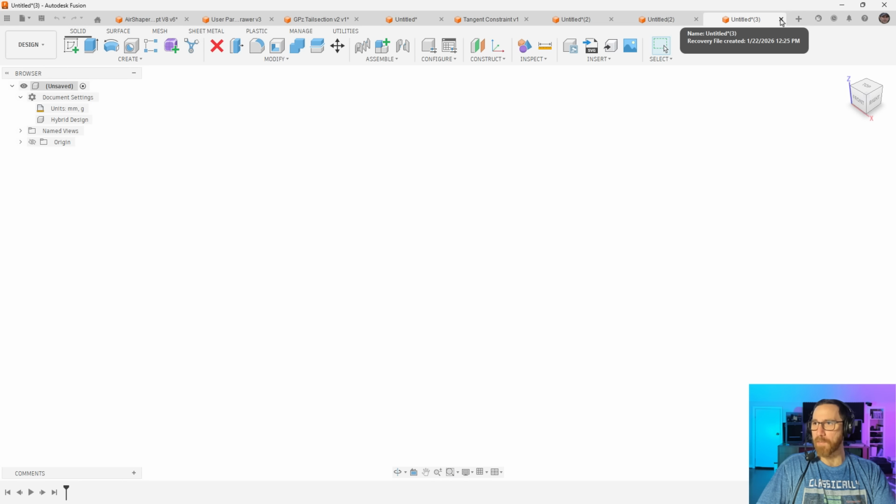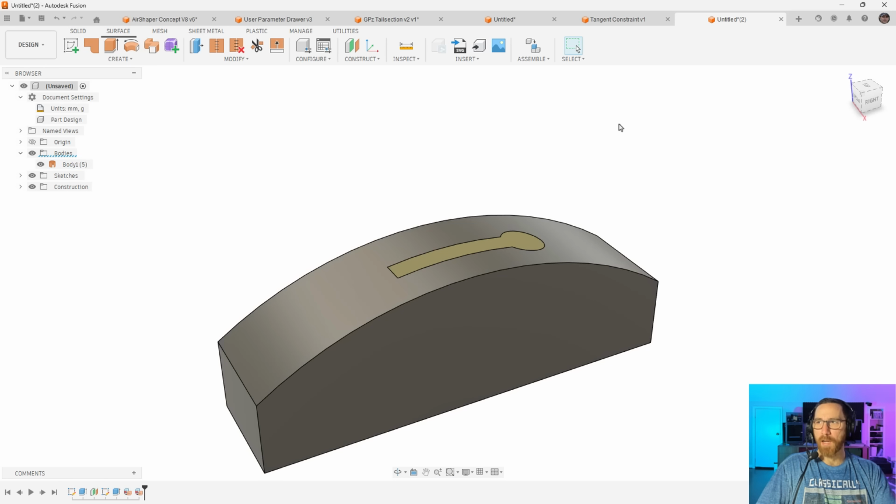I'm not going to really dive into it here, but this is going to be your default workflow. So if you haven't tried it out and played around with it, it's probably going to be a little bit of a disruption. Just know that you can convert between parts and assemblies and the hybrid approach, and you can kind of go back and forth with some limitations. But if you are looking at getting used to the way it works now, it's going to be more of a traditional CAD program where you have parts and assemblies, and then the hybrid is kind of like that option to use it how Fusion exists.